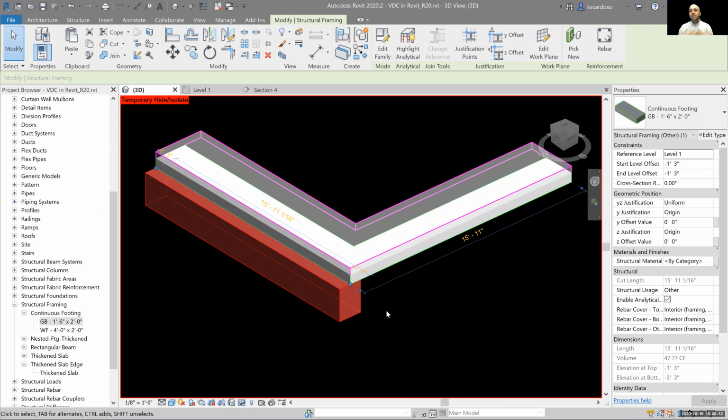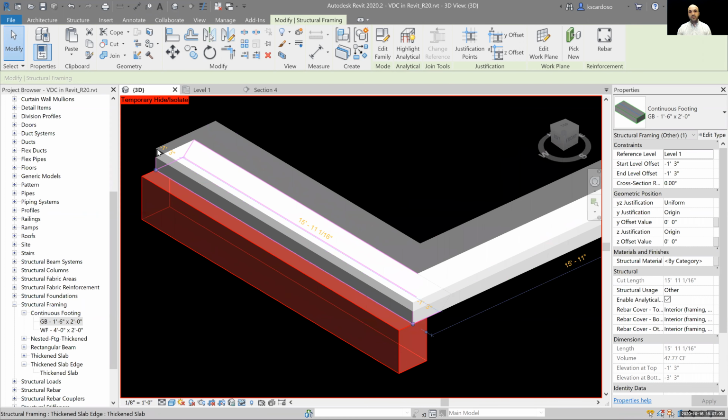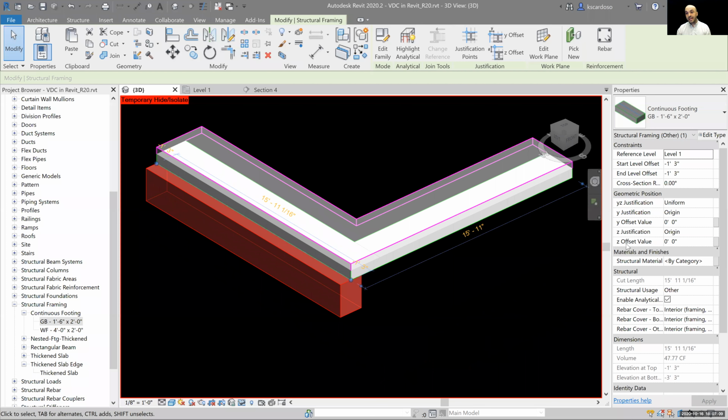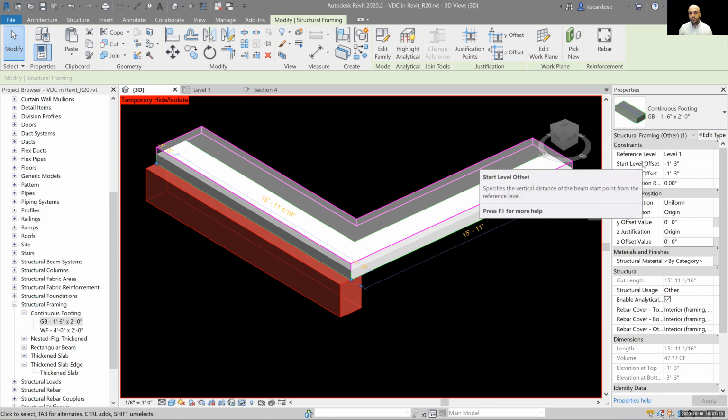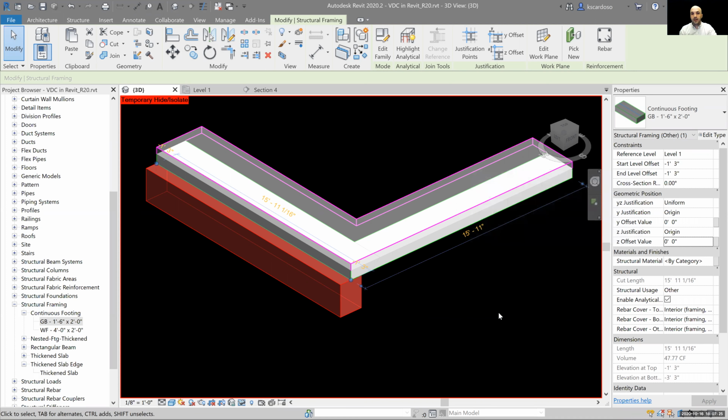So if you're going to commit to 3D snapping, commit all the way through. Try to avoid using 3D snapping and additional offsets, okay? Because when we did the original offset, right, we selected the top of this patio, and then we did a -Z offset of -1. But now you're doing more math, as opposed to just letting Revit do the math by selecting 3D snapping and letting these -1'3" total figure itself out.